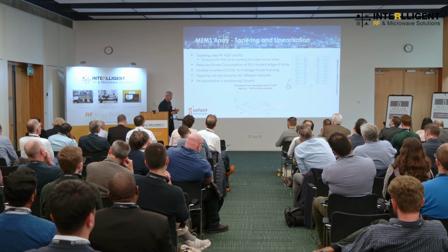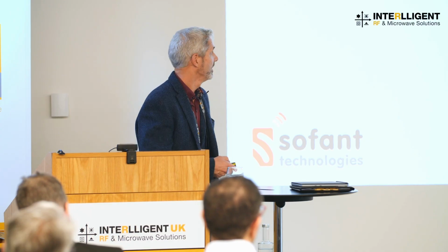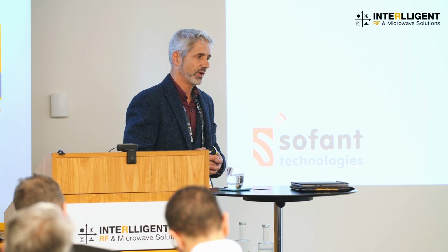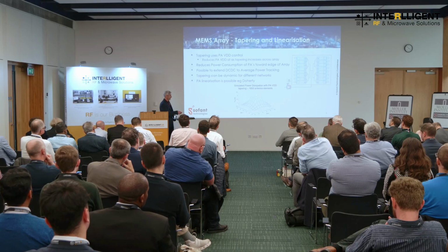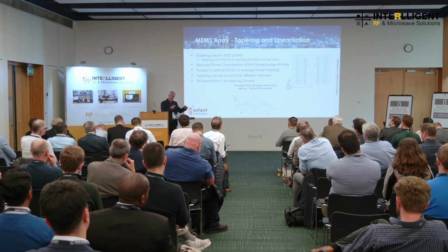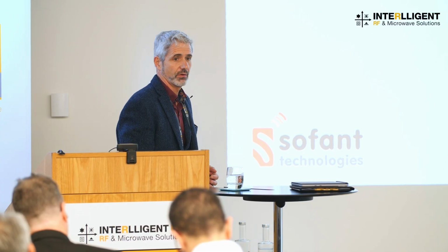I'll touch on this quickly because I think many of the PA people have talked about this and are much better equipped to discuss it than me. But we have some other benefits in this architecture. I mentioned before we have this DC to DC converter. This allows us, when you're working in the SatCom space, to manage side lobes, you have to taper. What that means, and this diagram demonstrates it, is that at the center of the array you have the highest power, and as you go across the array towards the edges, you reduce the power. That's called tapering, and it allows you to manage the side lobes of the pattern.